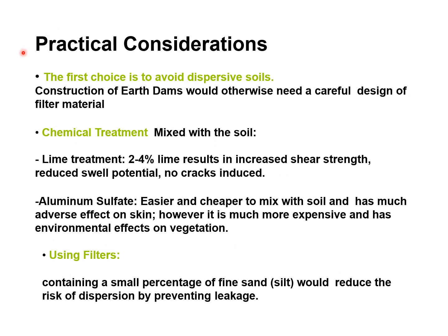Practical considerations. The first choice is to avoid dispersive soils. Construction of earth dams would otherwise need a careful design of filter material. Next consideration is chemical treatment. That means chemical can be mixed with the soil.